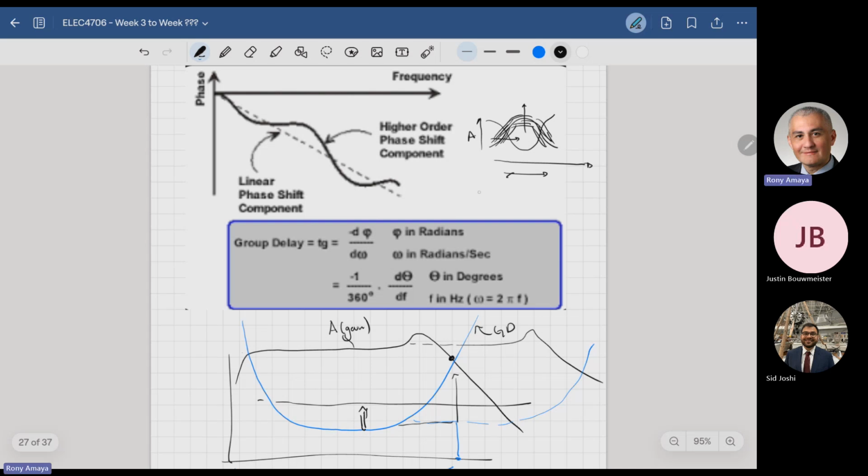Now, if you have a signal that does this, oops, that's supposed to be straight, then I could say that whatever happens here really doesn't affect it. We can ignore it. In fact, one of the tools that we use in the lab, because we've got noise coming from two sources. One is thermal noise, which we now know where it comes from, right? All this noise shaping and every noise source in the amplifier being referred back to the input. And then we have what's called transient noise. This transient noise is peaking and all this other stuff, right? And then you have them all coupled together.